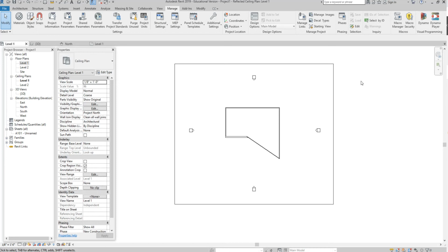And what that means is that when I am in AutoCAD and I'm drawing things, if I just type 10, enter, and I'm drawing a line, it will draw a 10-inch line by default in AutoCAD, right? In Revit, if I type 10, enter, it will draw a 10-foot line because foot is the default unit in Revit, okay? I think it's kind of the strangest thing ever because Autodesk owns both Revit and AutoCAD. I don't know why they can't be the same, but it's just something you'll have to get used to, okay? So in AutoCAD, the inch is the default unit. In Revit, the foot is the default unit.